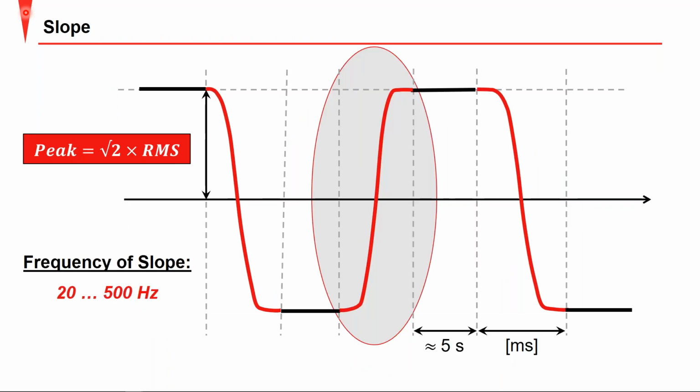Our other one that we want to cover here, which is mostly ideal for partial discharge testing, is our cosine rectangular waveform. As I mentioned previously, you have your fundamental VLF 0.1 hertz, so you have that 5 second half period. During your polarity reversal, you're again coming up with that resonant frequency that is representative and comparable to power frequency results. And so now you're able to perform a VLF test while performing partial discharge measurements during that polarity reversal that are comparable to power frequency results.